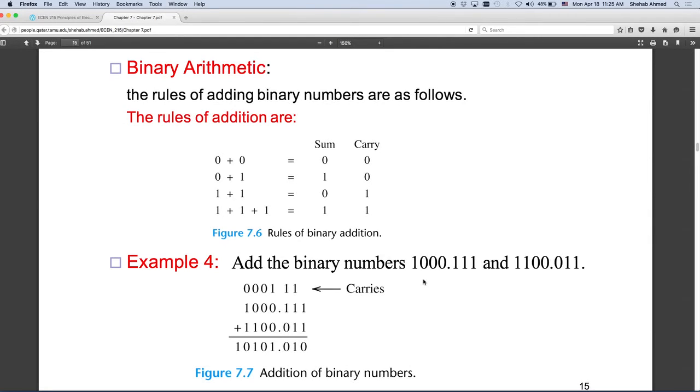And if you don't properly choose your data, so if you know that your numbers range between 0 and 1000, and you chose 9 bits, 9 bits represent 0 to 512. So you know from the beginning that you cannot represent 550. Right?